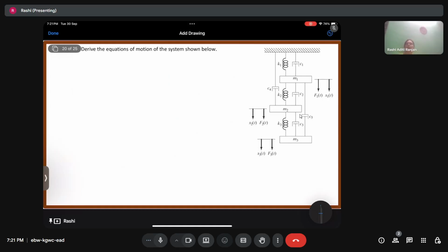equation of motion. Now you see, in order to find the equation of motion, we have several ways, right? Firstly, we have conservation of total energy, which is applicable only in the case of a conservative system, which has no damping present, so that is not applicable here. Second is the force balance, which is fine, but sometimes complicated because we have to think about what force is acting in which direction. Here, we have three masses, so we'll have to make three free body diagrams, and then sum up all the forces to get the solution.